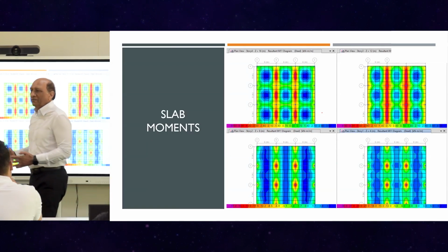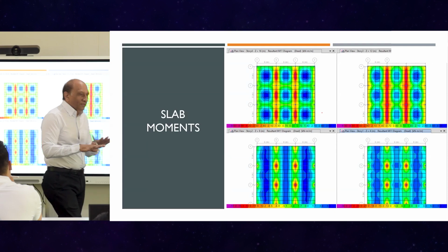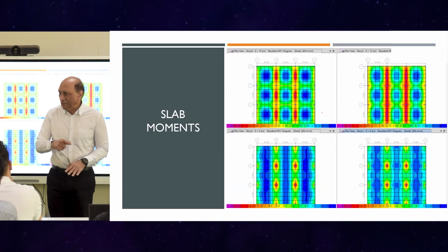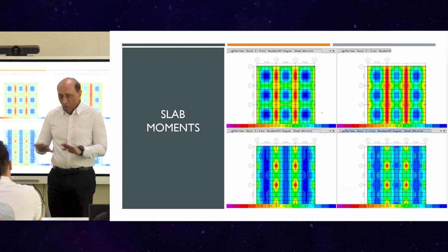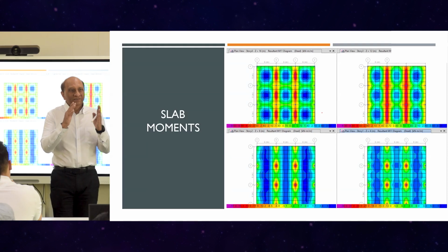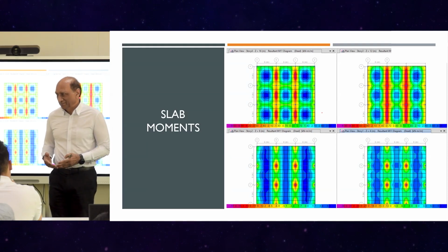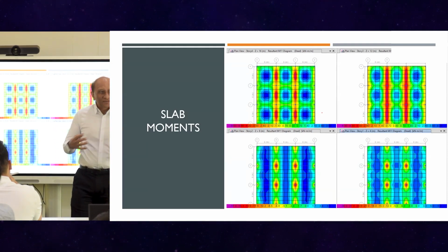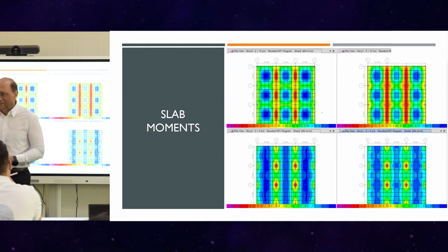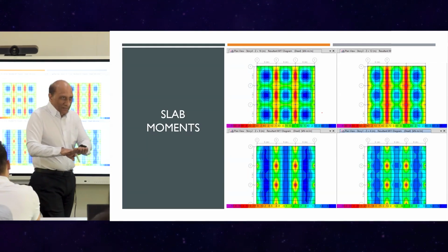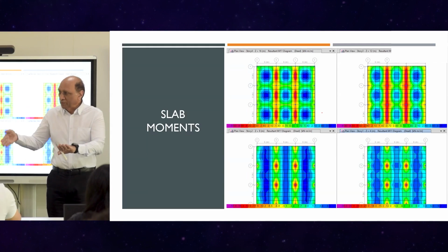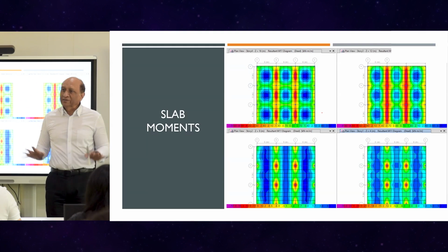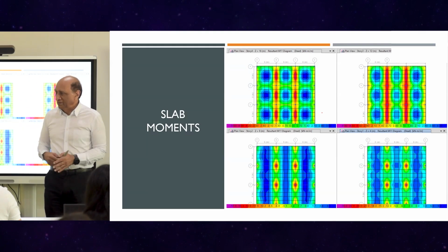So it's very important to note that when you design floor systems, you have to carry the entire load twice, not half this way and half that way. All the load will be carried in two directions because it's a two-way system. It is supposed to be carried in two directions. So please do not get this misconception that we have to only carry half the load in this direction, half the load in that. Yes, if you're doing a slab, you will carry half the load to this beam, half the load to that beam, but then the beam will carry that load back to the column. But here we are transferring the load directly to the column, so it must be full load in one step.